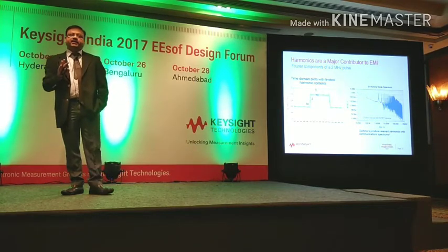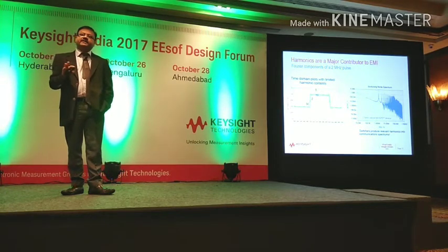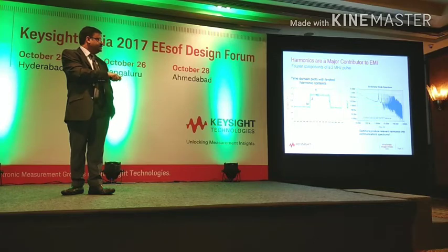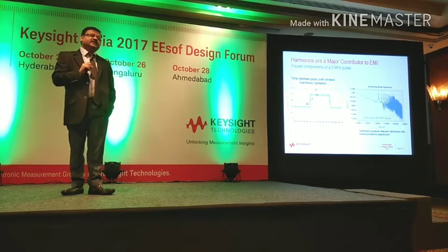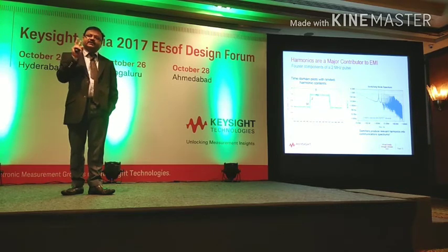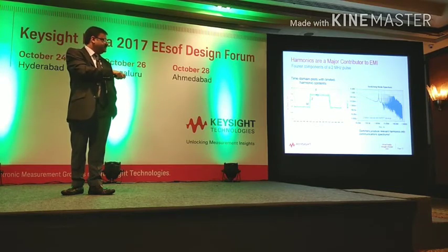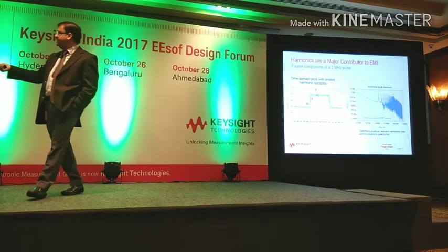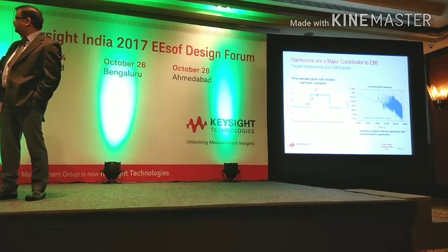But traditionally, power electronics guys have always been seeing these kind of waveforms. So this waveform is the same signal. It's a 2 megahertz pulse with a limited harmonic content. So if you take a 2 megahertz pulse and only consider two harmonics or two Fourier components, you get this red half sinusoid kind of waveform.